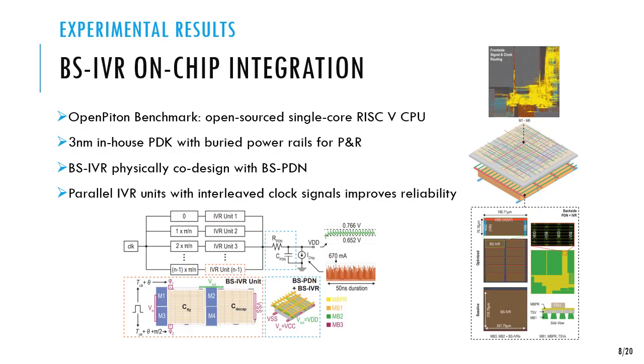So we have a baseline and optimized case, as discussed before, where the baseline tries to compensate for its inefficiencies by sizing up the capacitors, by maximizing the size of the capacitors, whereas the optimized case leverages the fact that we can have smaller weakly efficient IVRs in parallel and have their clock signals out of phase such that we can maintain the capacitor charge as long as possible. Therefore, the output ripple will be very small, at 10 millivolts, as we can see here clearly.